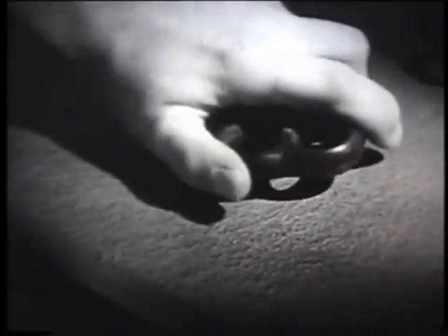If the electrolyte flow rate is insufficient, the dissolution products do not have time to be removed, concentration polarization increases, passivation and even gap breakdown may occur. An excessive increase in the flow rate significantly increases the hydraulic resistance in the gap, and cavitation occurs. The ohmic resistance increases, the rate of metal dissolution decreases, the purity of processing deteriorates sharply, and jet irregularities and grooves form on the parts.